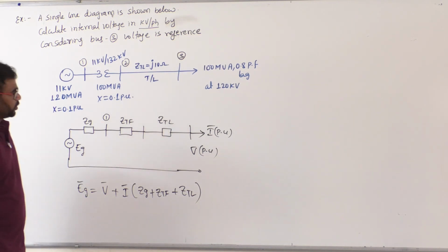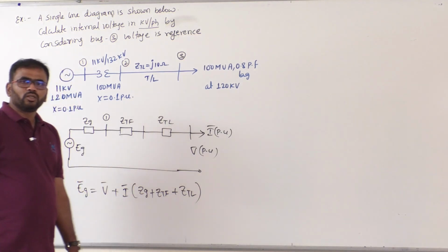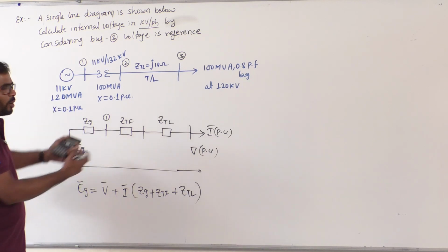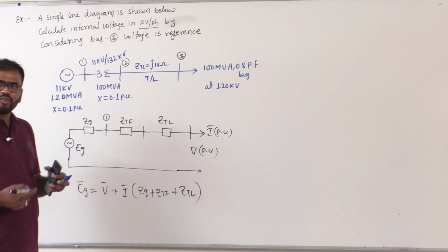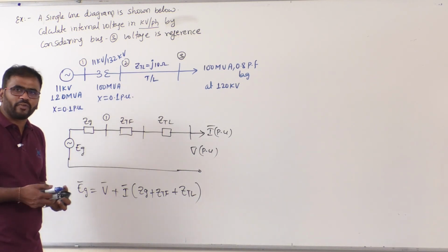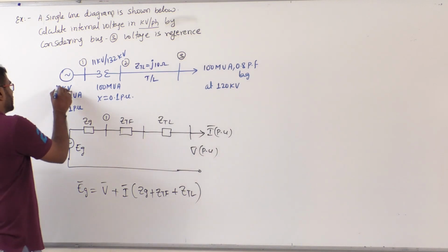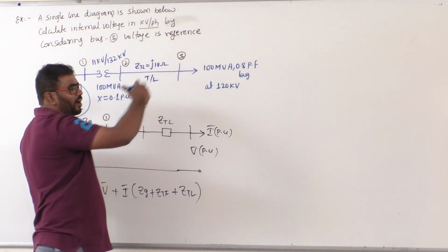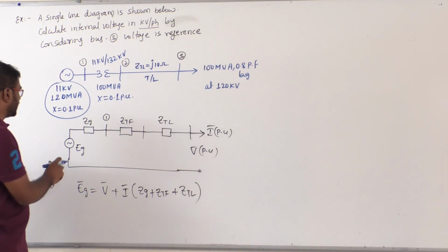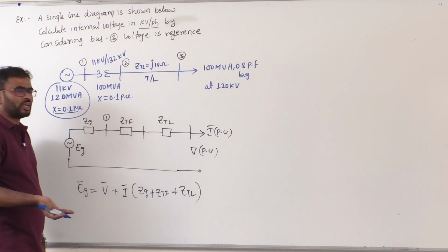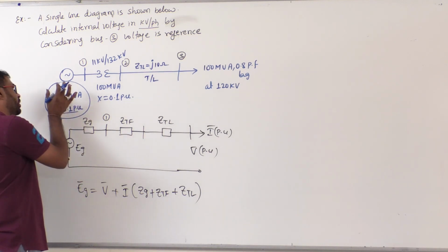But let's proceed from here. V. So V is the 120 kV here. But we have to convert this into a common base first. To do this analysis, we must convert onto a common base. So base value is not mentioned. That's why what I am doing here is I will consider the generator rating as base. By considering generator rating as base, I will convert the per unit reactance of all the elements onto a common base. If I take generator rating as base, then what? Generator per unit reactance will not change, because kVb old is 11, kVb new also 11.